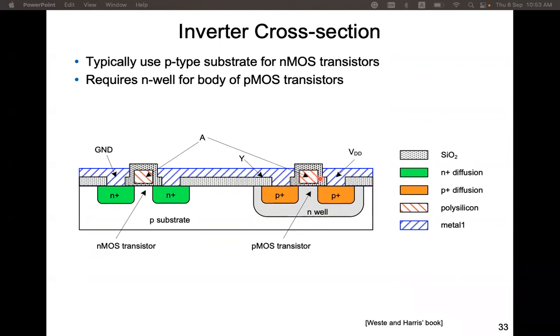This gray area represents the oxide layer, the insulating layer. For the PMOS, if we apply a low voltage to the gate, it attracts holes to this region, so a channel is established and current can flow through it. Basically, this MOSFET in the digital circuit serves as an on-off switch, with the control provided to the gate terminal.